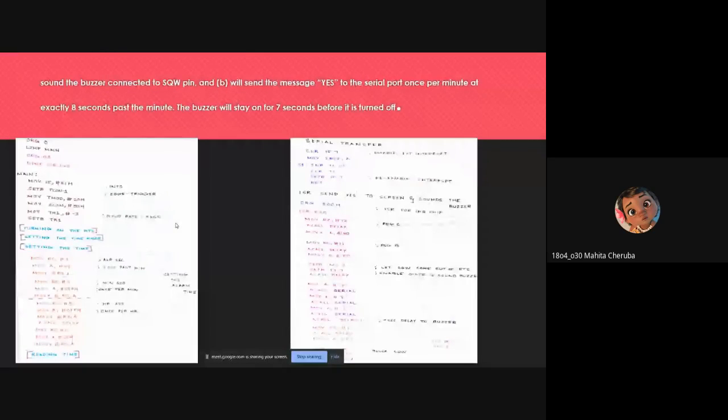And then comes our serial transfer. In a previous program we always used to set this IE bit 7, that is external interrupt. But why are we clearing or disabling it here? It is because this external interrupt should not get confused with our transmit interrupt. So that is the reason why we are disabling the interrupt as the first step.